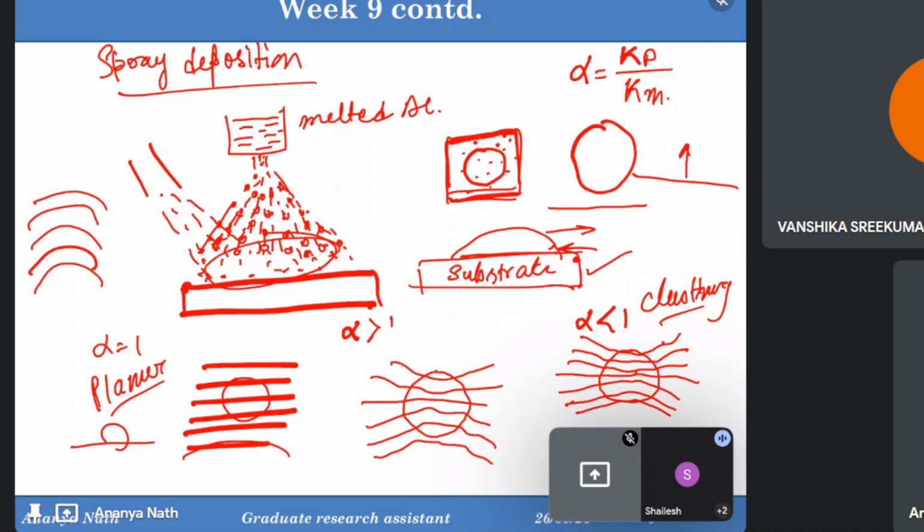Right. Yes, ma'am. Understood. Because we are coming from higher temperature to melting point. Yes. So that's what this interface will follow, the isotherm of melting point of that matrix material like aluminum, because we are cooling down the material. Now, suppose we were having 700 degree. Now we have come to 660 degree, which is the melting point of aluminum. Beyond 660 degree, means from 659 or 658, the solidification will be started. And there, these isotherms, solidification front, temperature gradient will play the role to get the proper distribution. Yes, ma'am. So obviously the melting point is the point where the things begin.